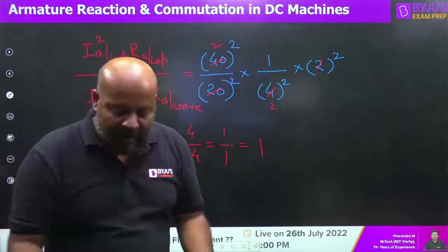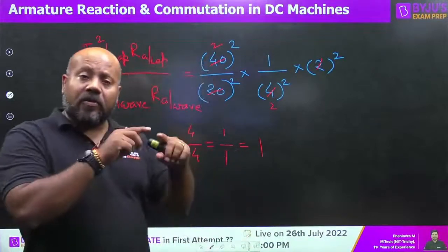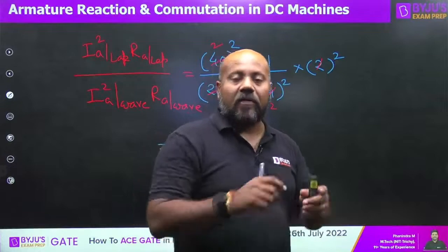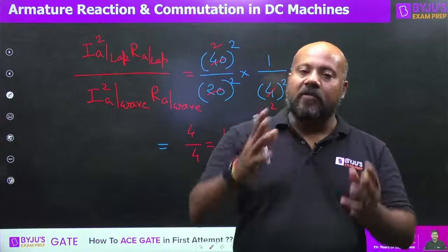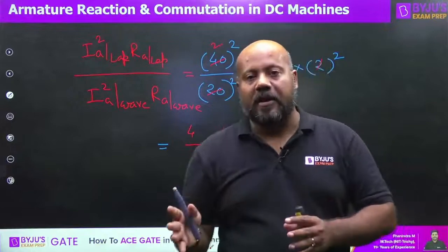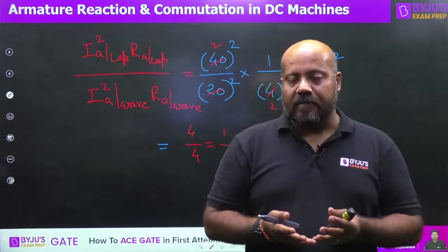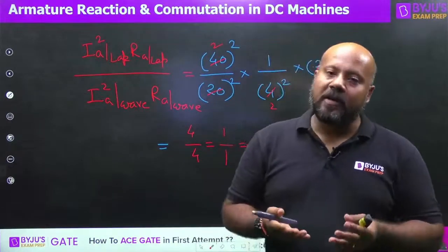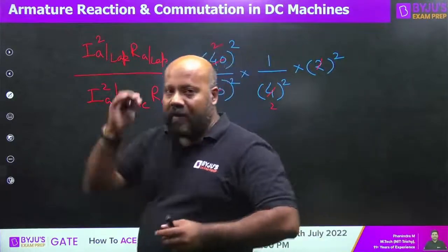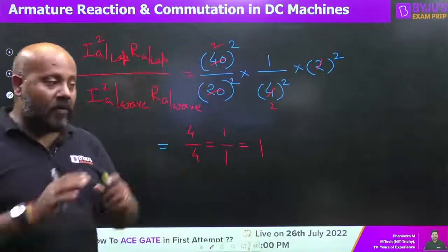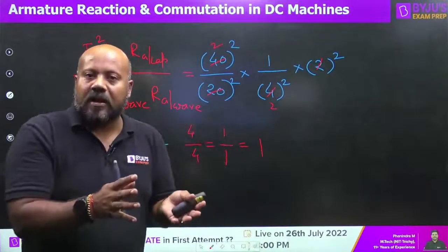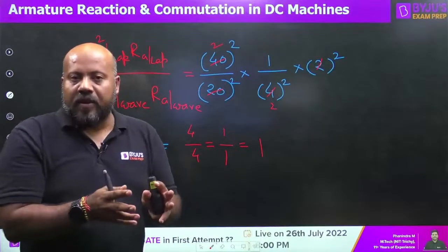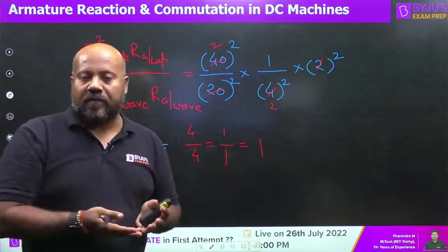So you can understand, if you have n number of resistances, whatever arrangement you want to do, you can do. Either you can change the voltage or you can change the current, but power will remain the same. And loss is nothing but a power. So if you have this intention in your mind that your machine is like a black box, inside there are some resistances, whatever arrangement you do, the loss is not going to change.